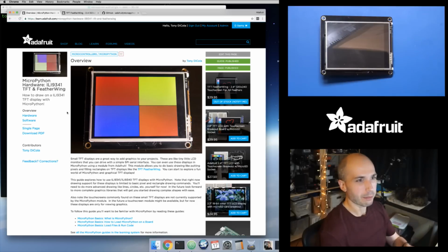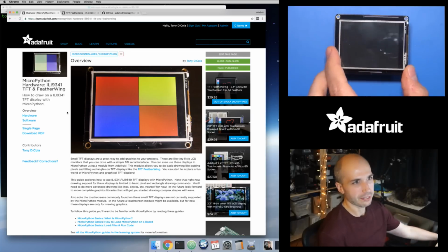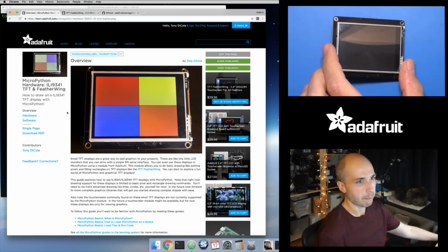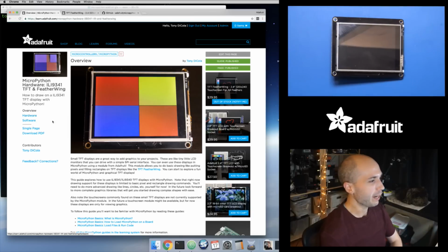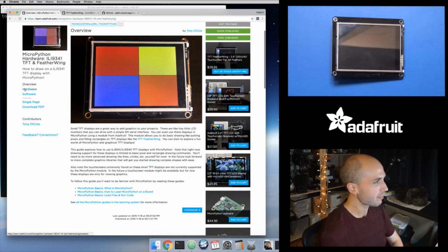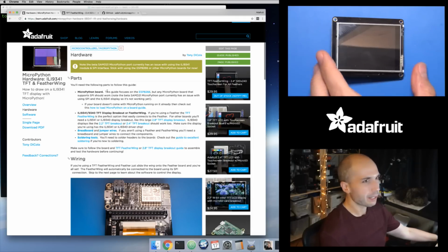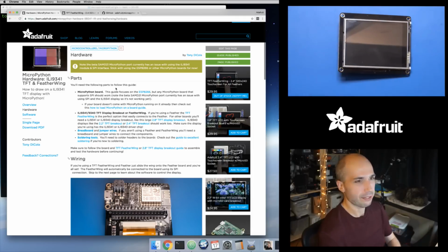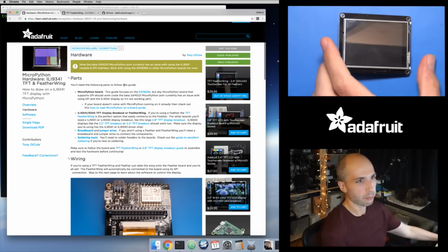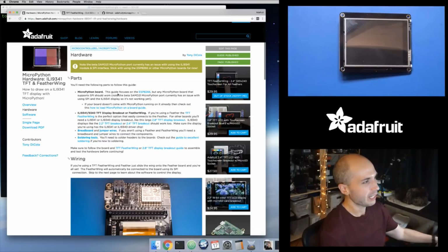But for now, in this video, I'm just going to show you how to set up and initialize this display, and just get to the basic pixel drawing commands after that. So let's just dive in. Hardware wise, it's pretty straightforward. You just need a MicroPython board. I did make a note, it doesn't currently work with the SAMD21 MicroPython port. There's some kind of issue with the SPI connection that we'll have to troubleshoot and figure out. Hey, it's a beta port, not everything works yet, but it does work really well with the ESP8266 port that I was just trying it with for this example.